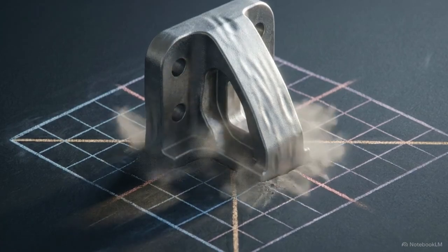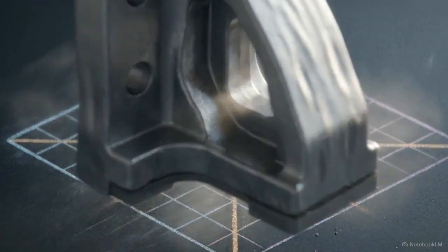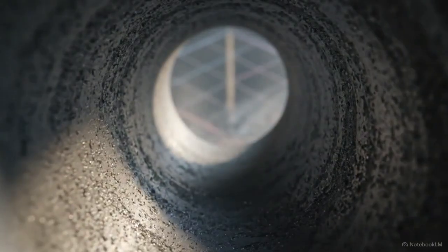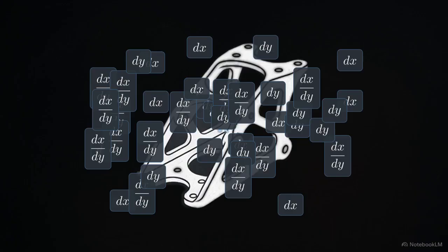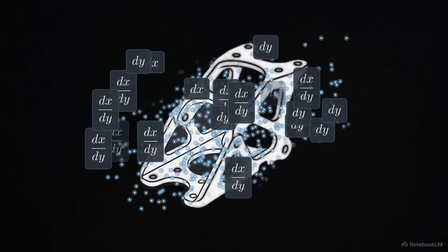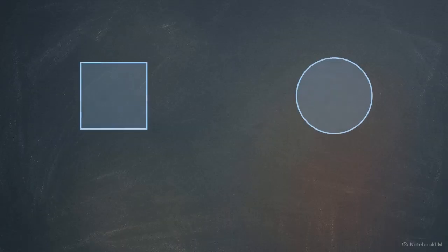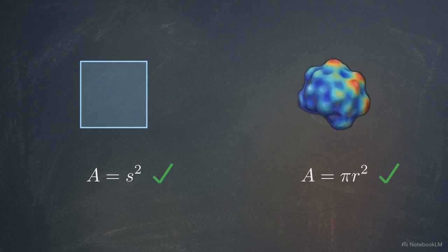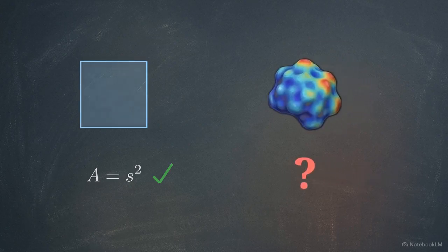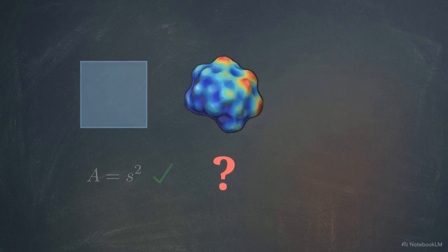When engineers analyze a continuous physical structure, like an aerospace bracket under active load, they hit an immediate mathematical roadblock. To predict how a material will flex or fail, we formulate a boundary value problem. This requires writing differential equations that describe the physical behavior across every microscopic point of the domain. For simple textbook shapes, we can find exact analytical solutions to these equations, but for complex geometries, an exact solution is often impossible to find.